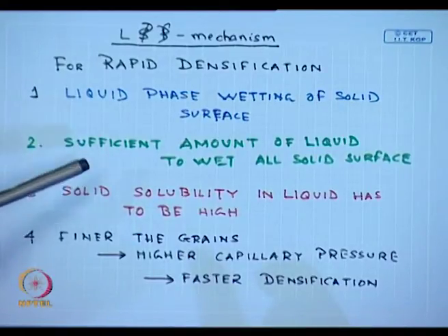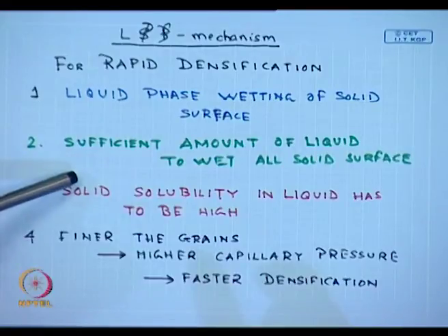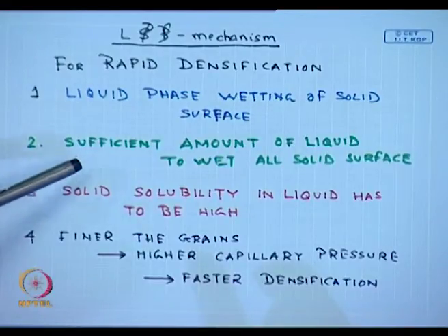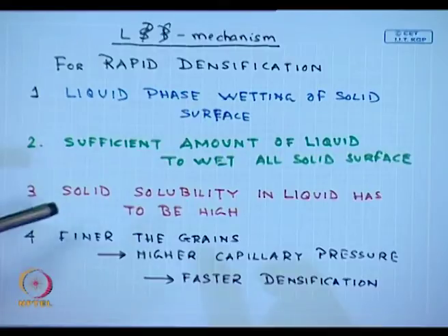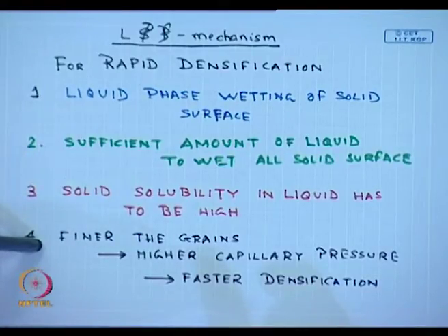The solubility of the solid in the liquid has to be high. Finer the grains, the higher is the capillary pressure. I had told you why. And as the capillary pressures are higher, the densification rates shall also be higher.